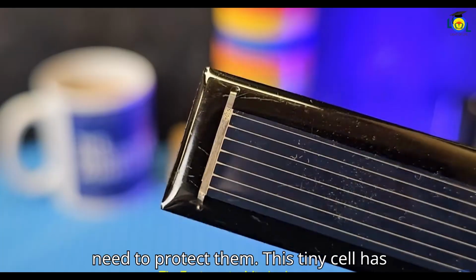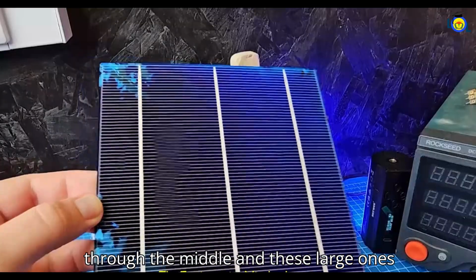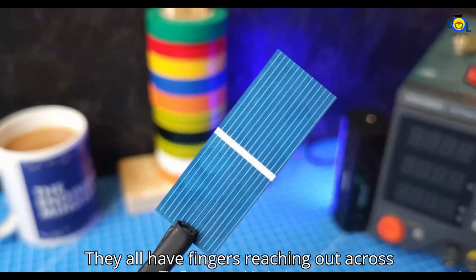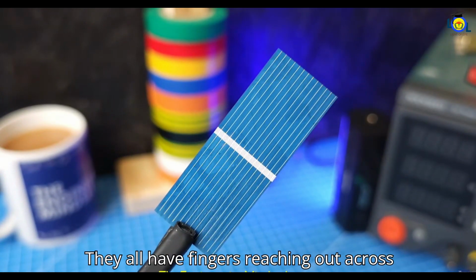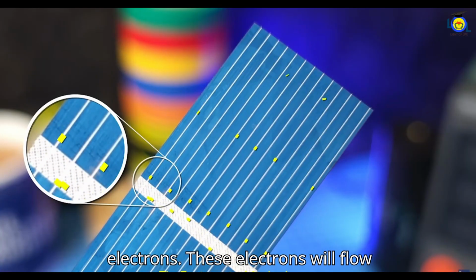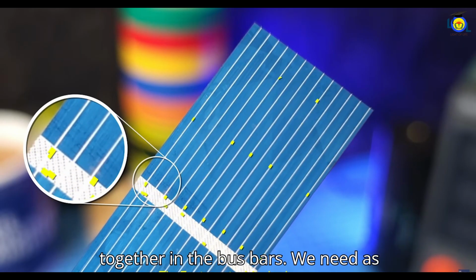This tiny cell has a bus bar at the very edge. This one has one going through the middle, and these large ones have multiple bus bars through the middle. They all have fingers reaching out across the silicon to collect the free electrons. These electrons will flow along the fingers and collect and flow together in the bus bars.